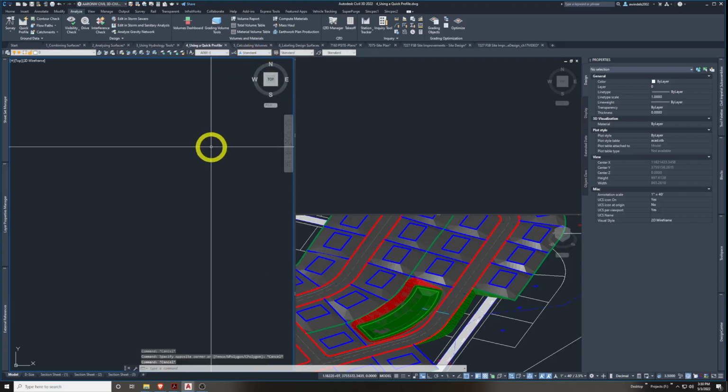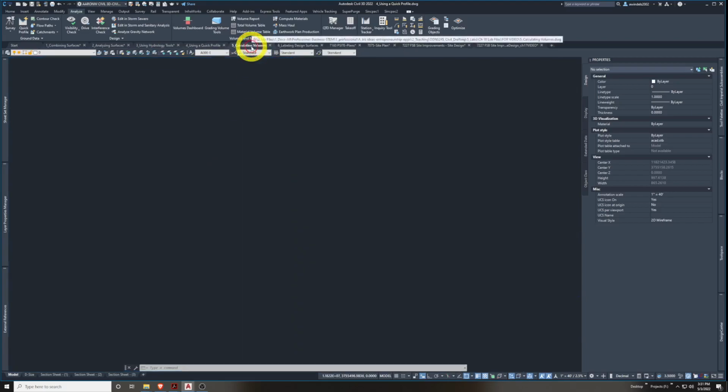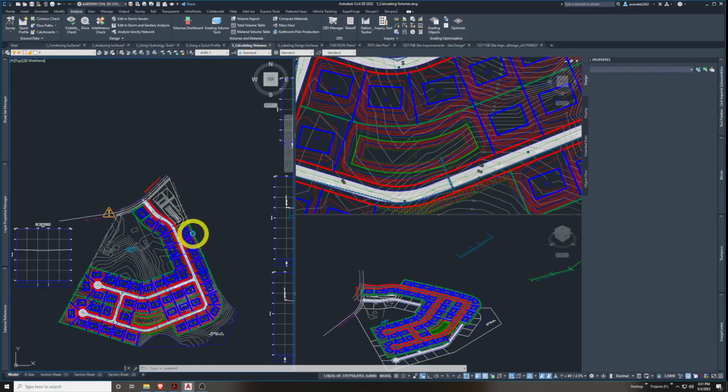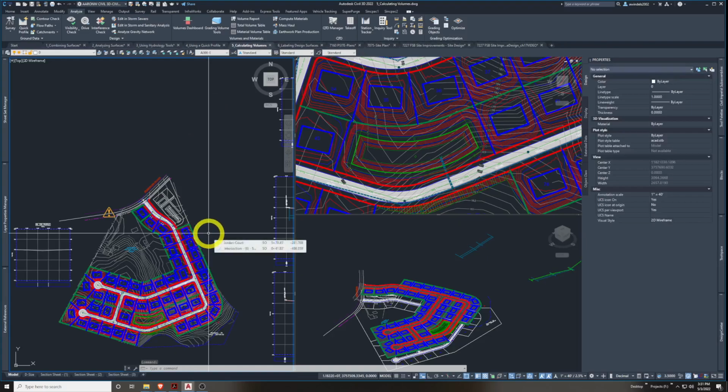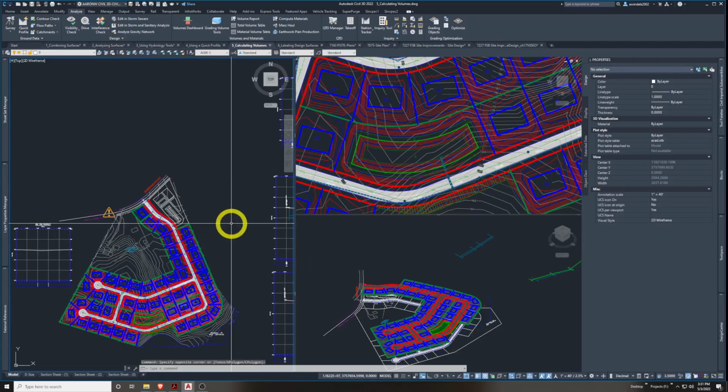So volume surfaces are pretty important for 2 reasons. First of all, on any site you want to see, construction is very expensive, especially land development. It's the biggest expense. So the big 2 questions you want to a lot of times answer is how much earth must be removed and of what type of earth. So do we need to bring a bunch into the site, import, or do we need to transport a bunch out of the site, export? Those are the 2 key takeaway questions, and they're very critically vetted numbers that get very nitpicked.